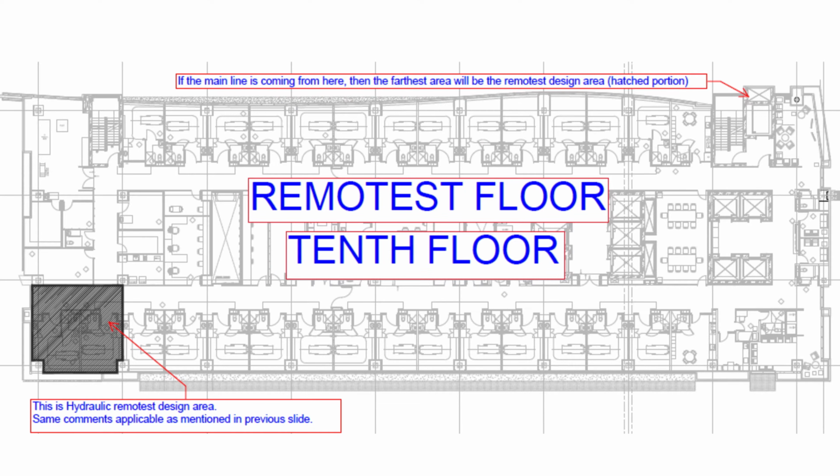right side of the staircase, then the farthest area will be the left side, which is shown on your screen. So the remotest design area will be on the left side. The same comments which I explained in our earlier slide will be applicable if we consider this particular area as the hydraulically most demanding area.